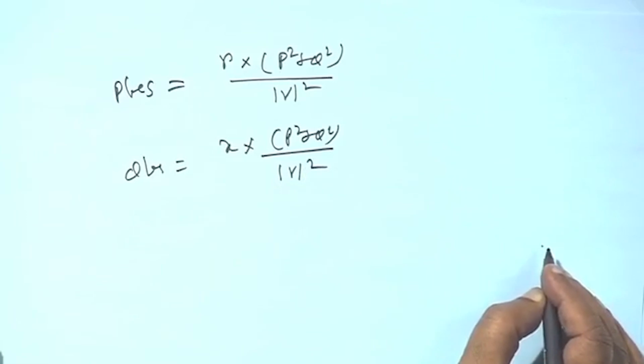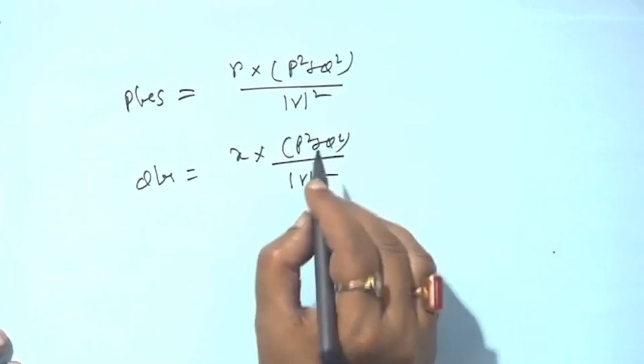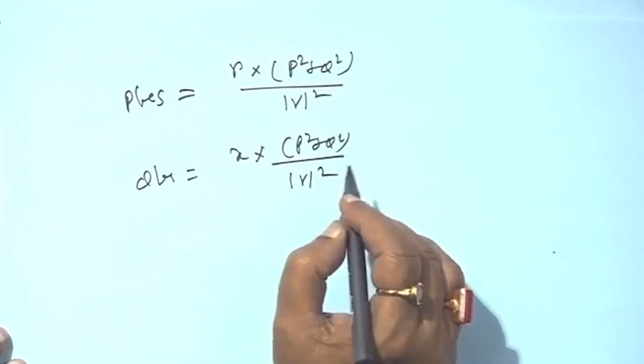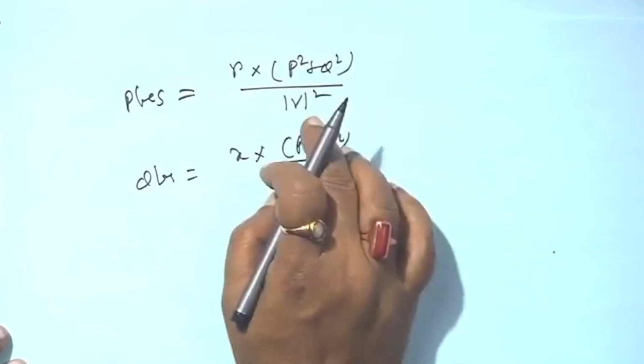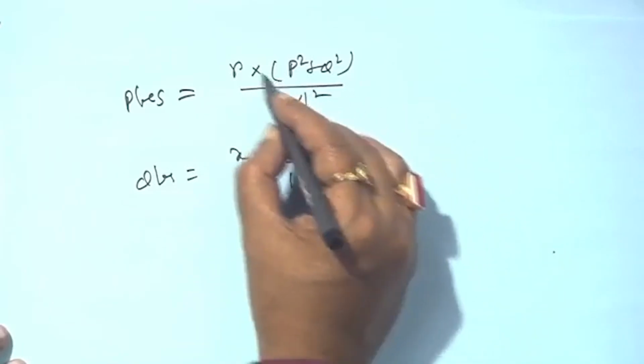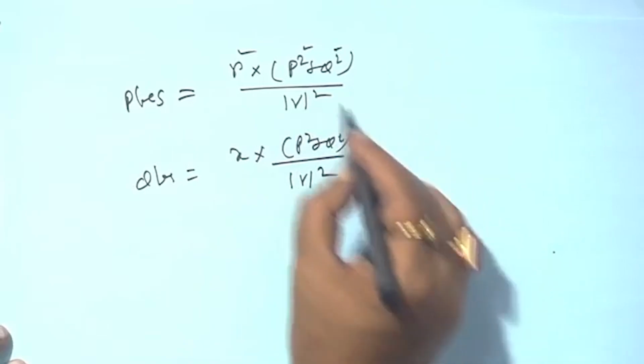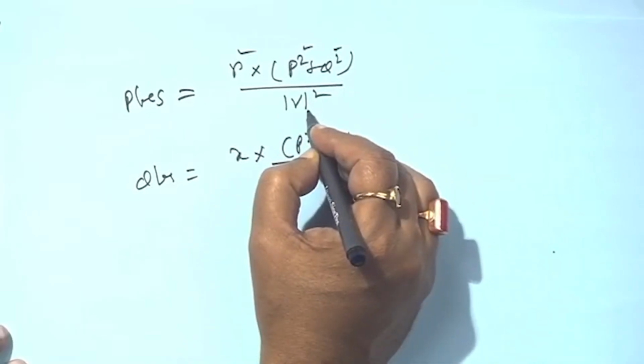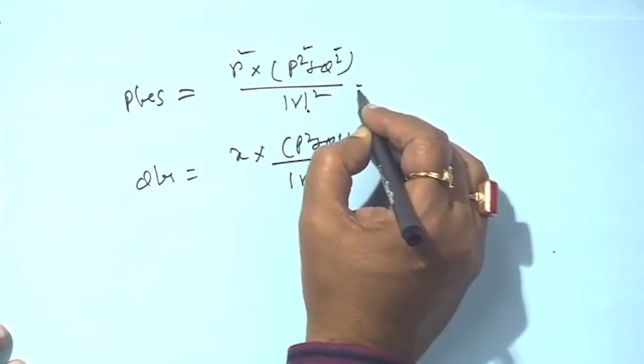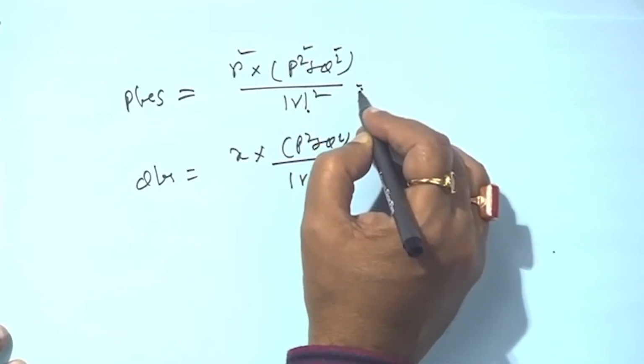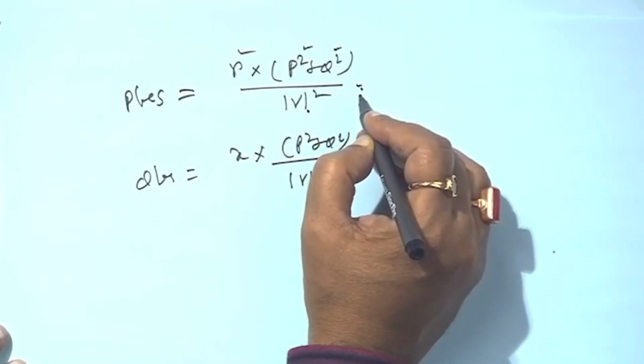Because of the series capacitor placement in the line, the voltage is improving. If the voltage improves, although the rest is unchanged, there will be a reduction in power loss, but that is quite less.